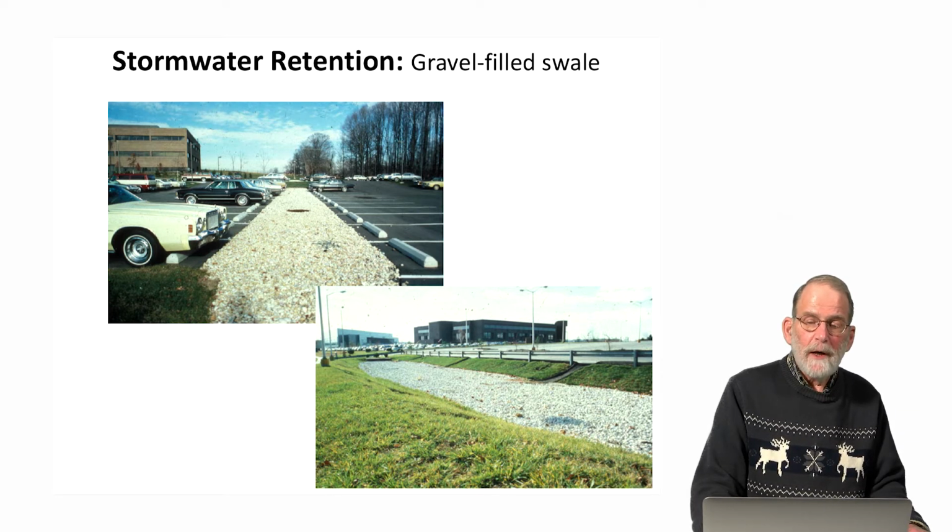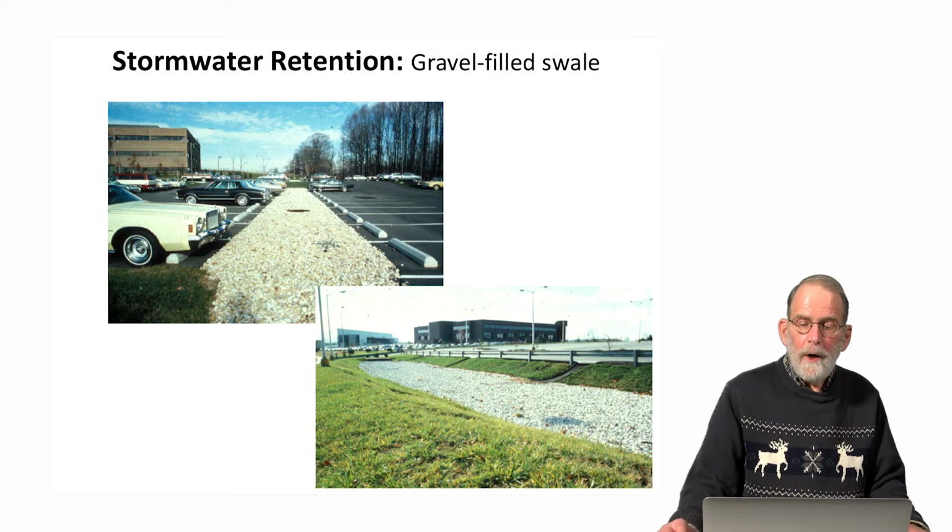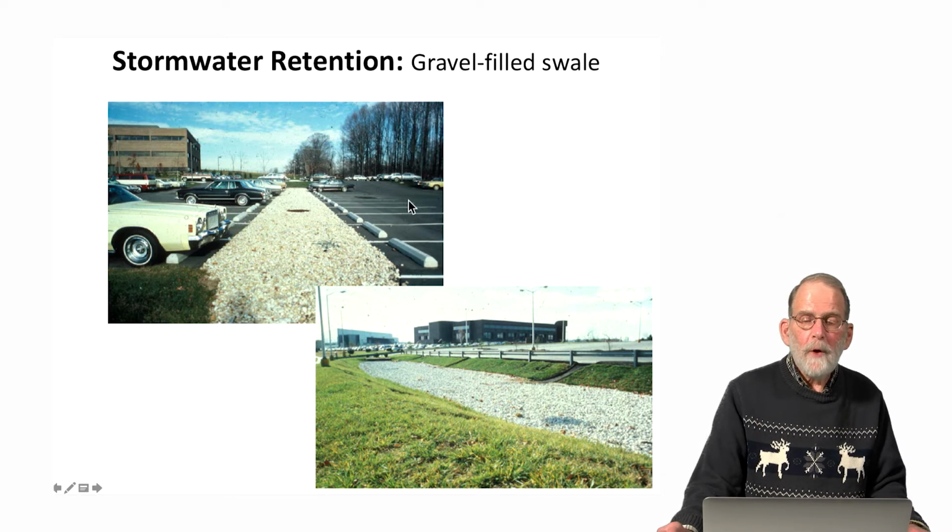In this instance, we're talking about gravel-filled swales, where in a parking lot context, we have islands in between the parking bays that are filled with gravel, and water flows across the impermeable surface directly into these gravel trenches, these gravel swales. The condition in this landscape is similar to the diagram that I showed you earlier, where water infiltrates down through the gravel into the adjacent landscape.